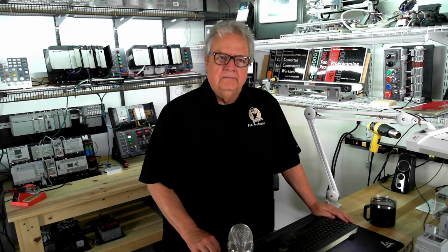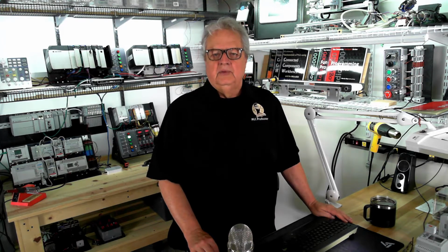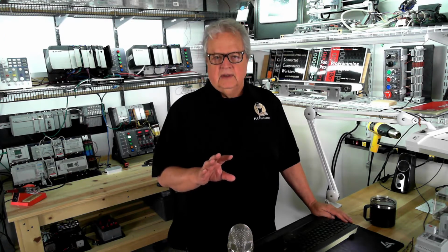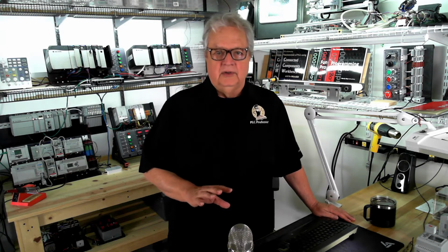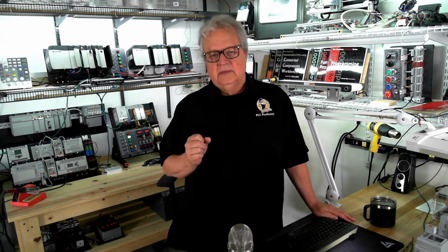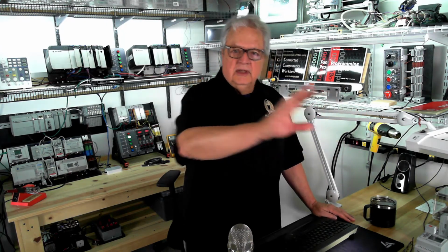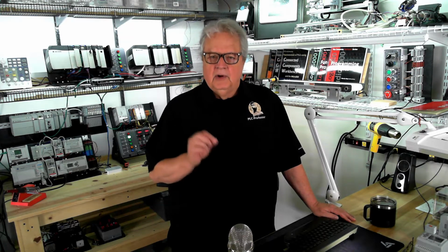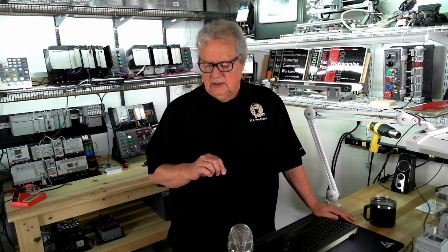an idea to make it easier for you to simulate momentary push buttons. So the start-stop buttons on this system, both for the system and individual conveyors, they're momentary spring-loaded. You press them and release them. You know, close, open, or it's closed and when you push it opens, then you release it, it goes back closed. So it's a momentary contact. But we're not really using I/O yet. We're not going to use actual switches.